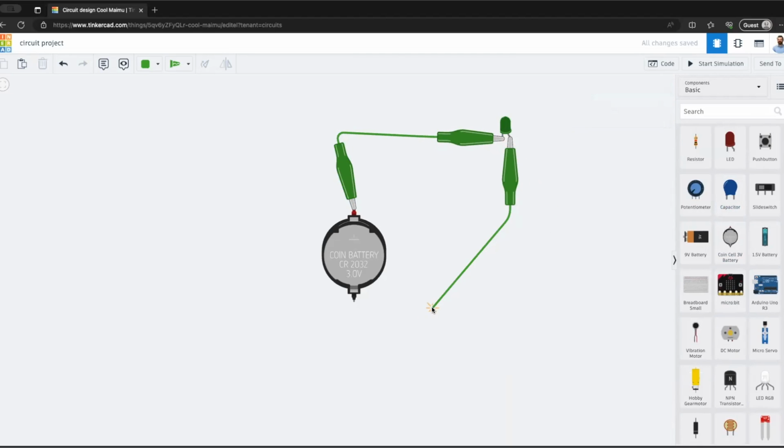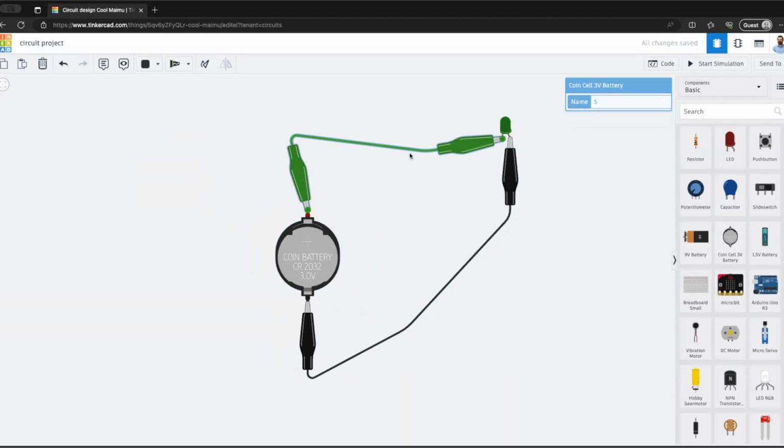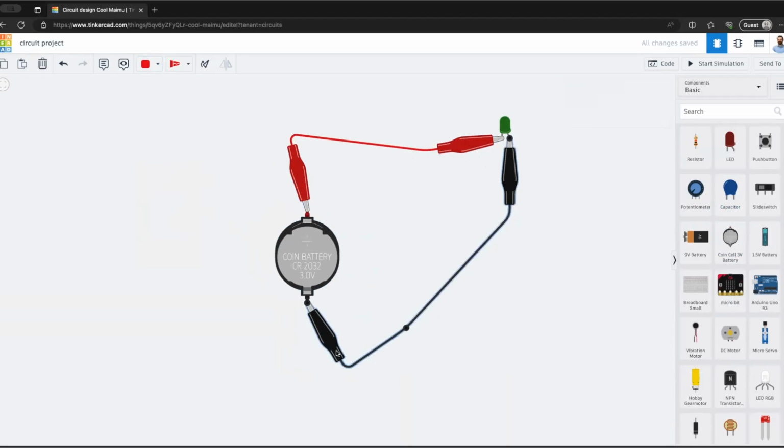So I'm going to hook up 2 wires. All right. And I'm going to go ahead and hook this up like this. And I have 2 different color wires. Technically, red is usually the color used for positive in a DC electronic circuit, and black is what we typically would use for negative. And you'll notice that my light's not turned on. And there could be a couple reasons for this. The first is because I haven't actually sent any power to my circuit.